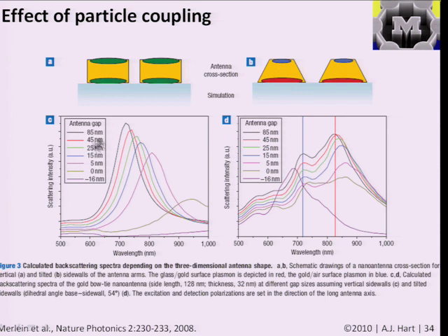And as the spacing changes, they're calling it the antenna gap, saying this kind of acts like a little antenna or a beacon. The position of the resonance peak shifts, and in their theoretical case where they had these kind of trapezoidal particles, they saw the emergence of 2 peaks, which is a result of the different shape and the resonance that is supported in that shape. I don't think, if you look back at their experiments, they saw as much of a shift as they predict theoretically, but the shift itself was certainly there.